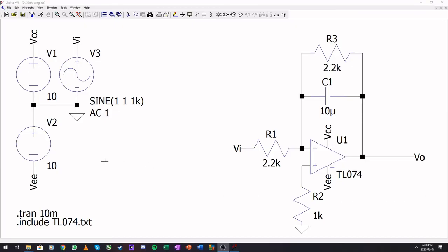So the first thing that I want to show you in simulation is basically I have a sinusoid set up here with a 1 volt peak and a 1 volt offset, and it's how to use an integrator to cancel any DC voltage. So I placed the resistor here to discharge this cap, and I put in a huge capacitor to capture any of the DC voltage.